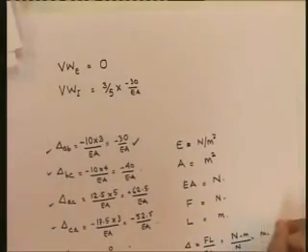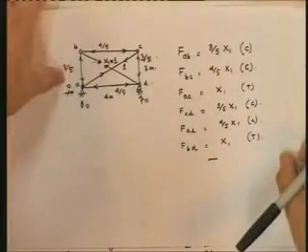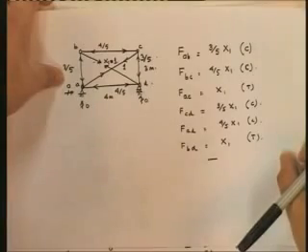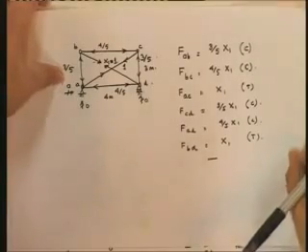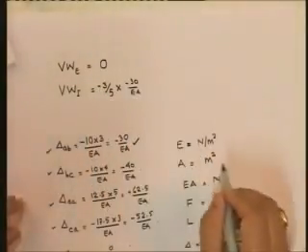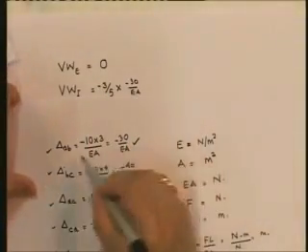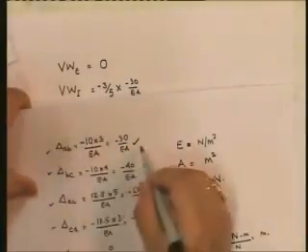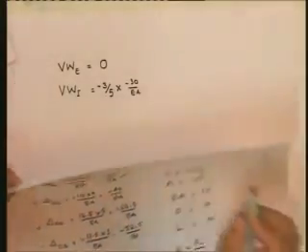That gives me the work done by the virtual force in AB, which is 3 by 5. Note that this is compressive, so the compressive force is going to be given by minus, undergoing the real deformation in member AB, which is minus 30 by EA.